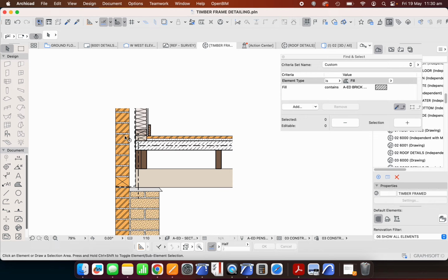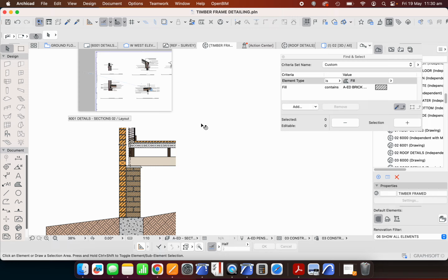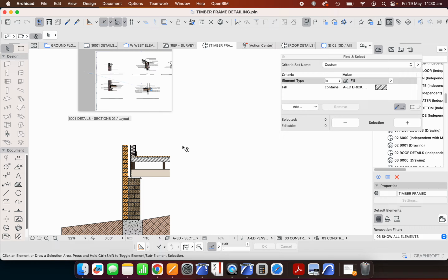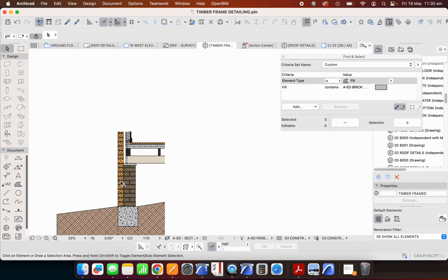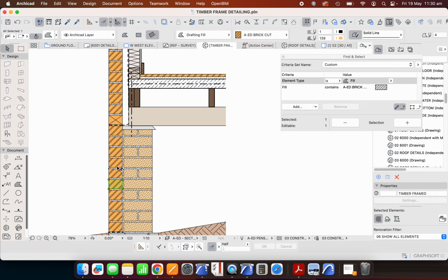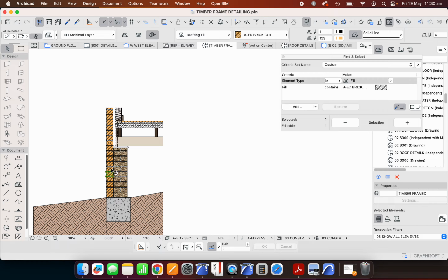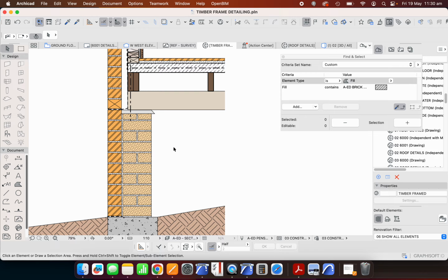I could also have this up at ground level, and I may also have this higher up as well. I may have this up underneath windows in addition. So weep holes up there. The idea is I want to get all moisture out of this building as readily as possible. I may also have ventilation. I probably will have some type of ventilation down here as well. Subfloor ventilation. I'm not going to represent this at the moment. But the idea is I need to ventilate this space because I can't have it building up with moisture because I've got exposed timbers.